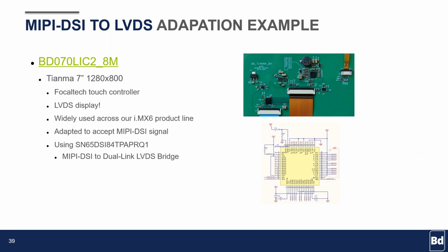Now, the next daughterboard is still about display output, but from a different technology. For those who have been using the i.MX 6 processor in the past, you most likely had to use LVDS display. This has been our case for many years, and over time we found displays that were perfect for our customers, both for their quality and price. So using the same LVDS display for Nitrogen8M Mini really was of interest to us.